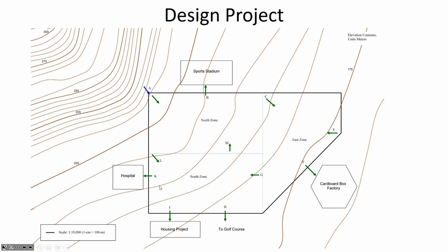So what pressurizes the network? Well, it's where you put the reservoir on the hillside. If you put the reservoir really high on the hillside, that's going to deliver a large pressure to junction A. If you take it too high on the hillside, then at night, when people aren't using much water, the static pressure in the network, meaning the pressure at zero flow rate, is going to exceed the maximum of 850 kilopascals. So it's this balancing act, not only of where's the right place on the hillside to put the reservoir to get that optimal pressure, but then also how big the pipes should be.